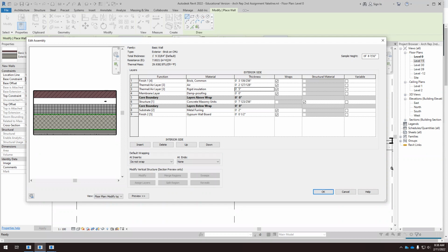This is what we have in residential buildings. But this is a commercial building, and we don't have this layer with studs and then plywood. We have the concrete masonry unit. Okay, so this air cavity we have here with the metal furring, it's this. Okay, so this is the gypsum wall. If we remove this board, we would see the metal furring there. But it's not a stud. It's not a wood stud.